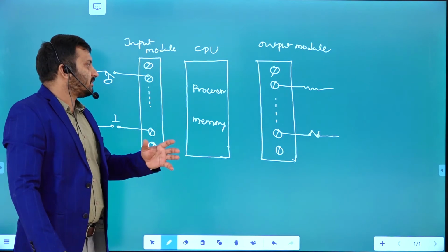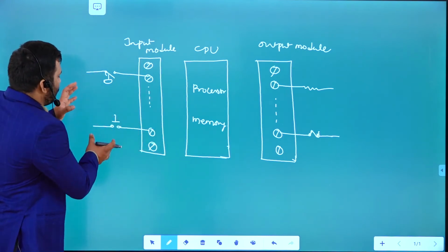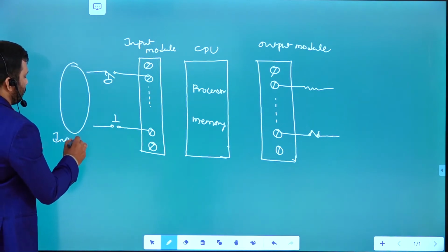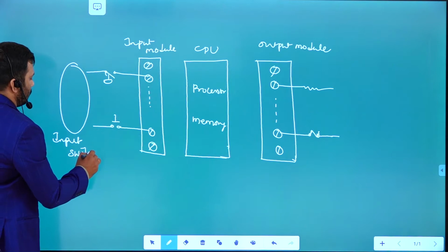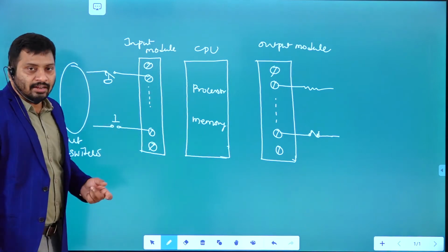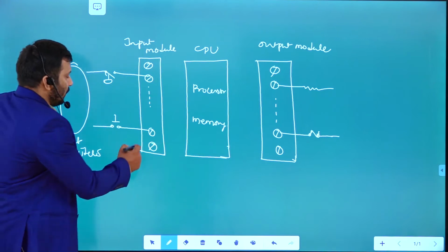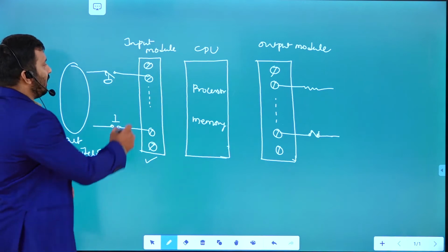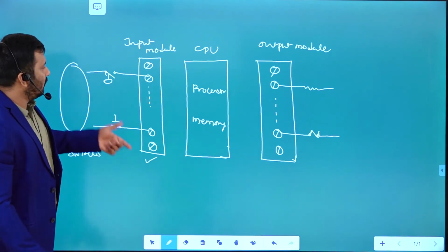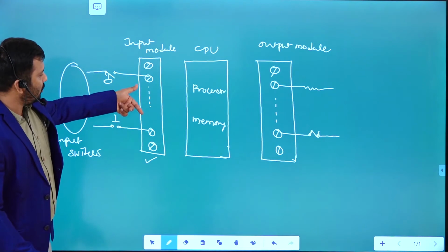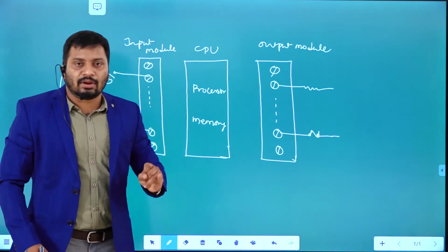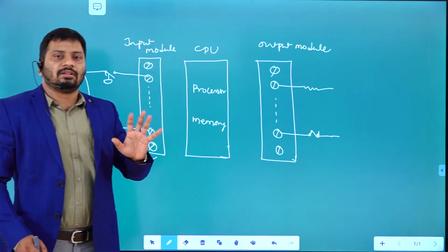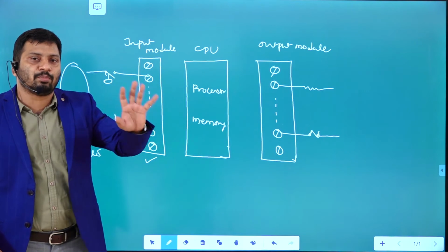In previous classes we discussed input sensors and the different input switches normally used in industry. Hardware-wise, we have seen input modules with different numbers of terminals along with the power supply and ground terminals. AC modules and DC modules, and the number of terminals, vary depending upon the application: 4, 8, 16, 32 and even 64 terminal input modules are available.